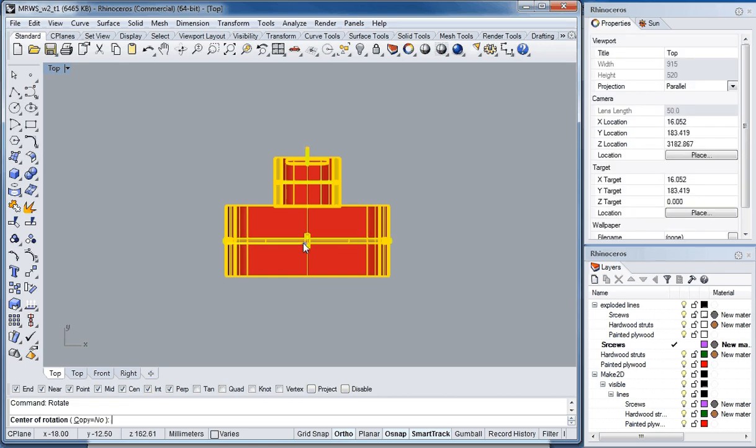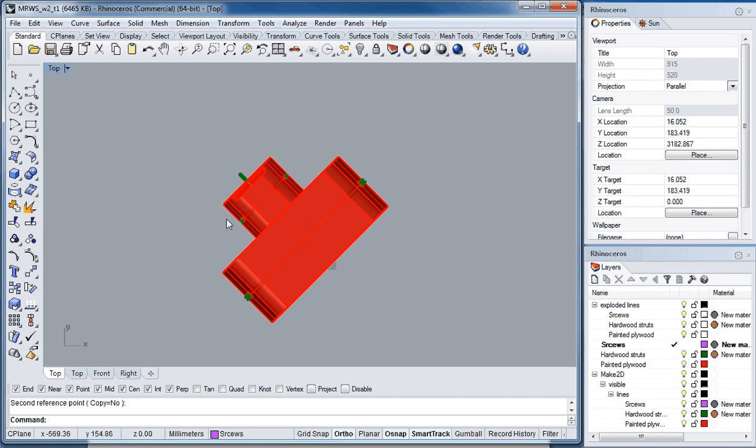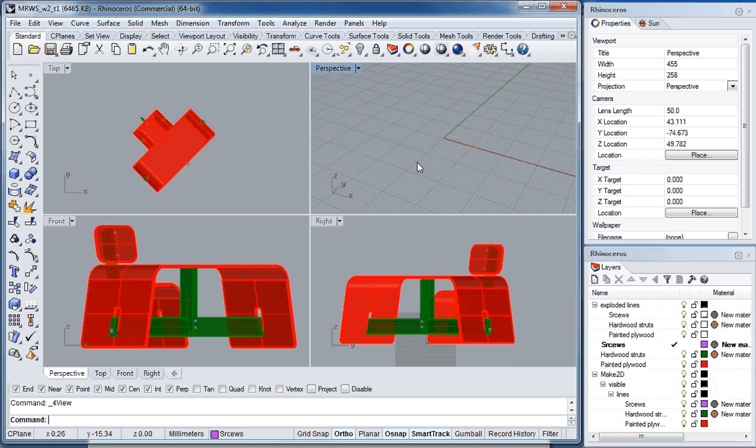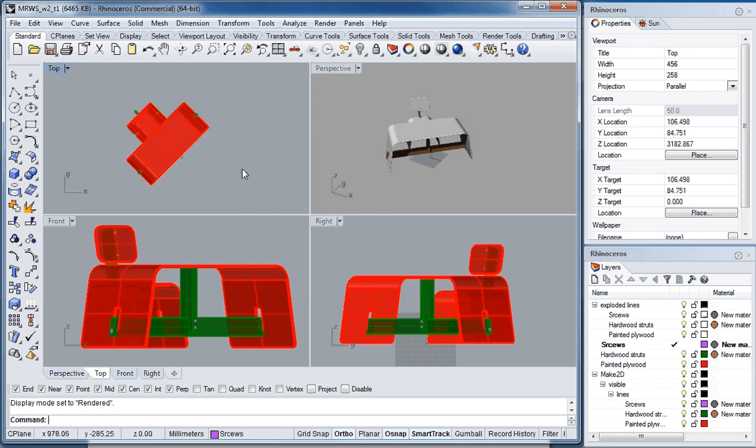So I'm just going to demonstrate that by rotating our table and chair 45 degrees. And so what you see now is if we go back to our world viewport system, to our viewport layout, you'll see that the front view and the right view are now sort of oblique or off to an angle like this, and so what we actually want is an orthogonal view to the front of this table. So the way we'll do that is by setting up a new construction plane or C-plane.